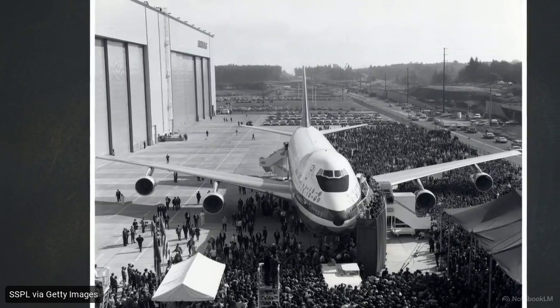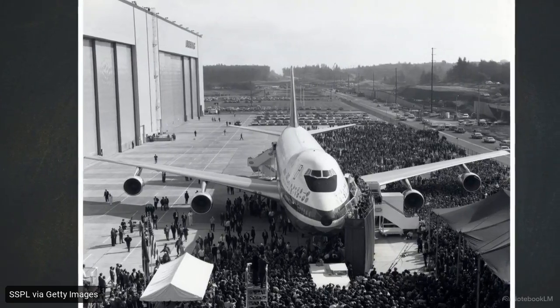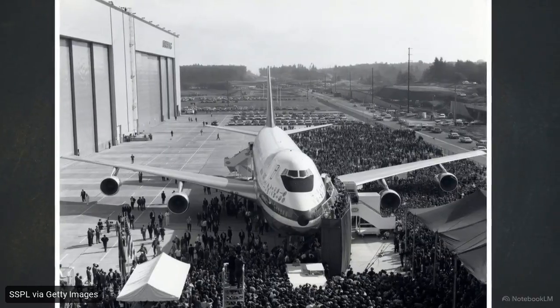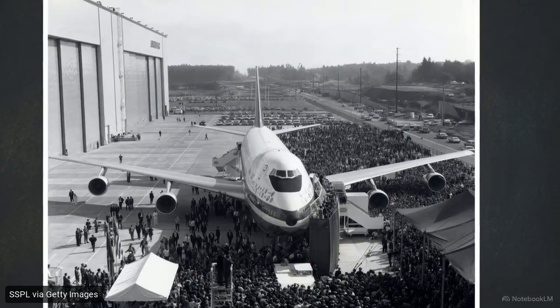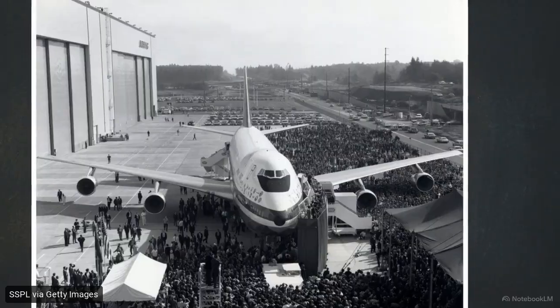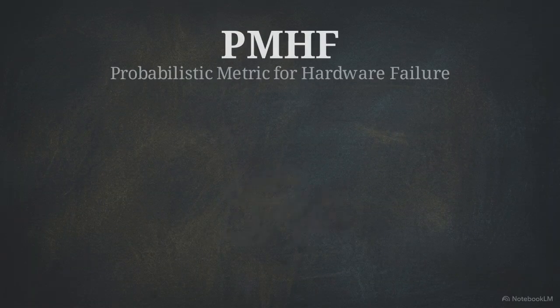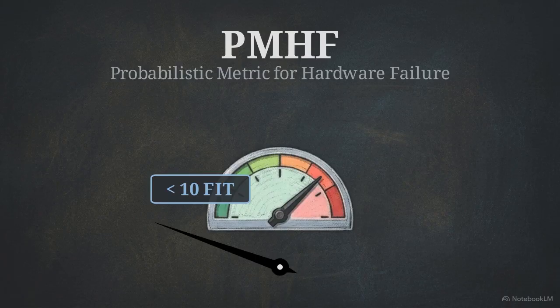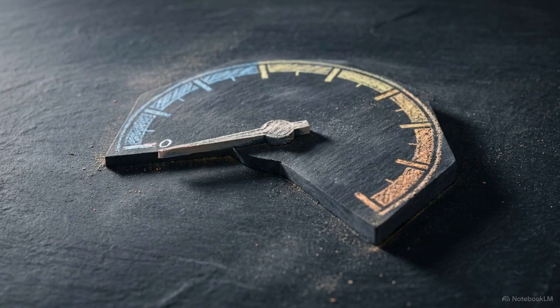The methodology proved so reliable, it moved into commercial aviation validation, securing the Boeing 747 before becoming a mandated tool for mass-market automotive networks. Today, ISO 26262 requires engineers to use FTA to prove an ultra-strict quantitative target called the probabilistic metric for hardware failure. For the highest risk category, ASIL D, the system must demonstrate fewer than 10 failures in a billion operating hours.